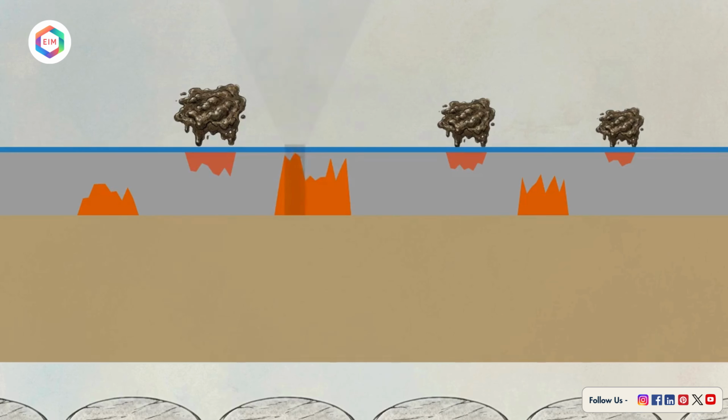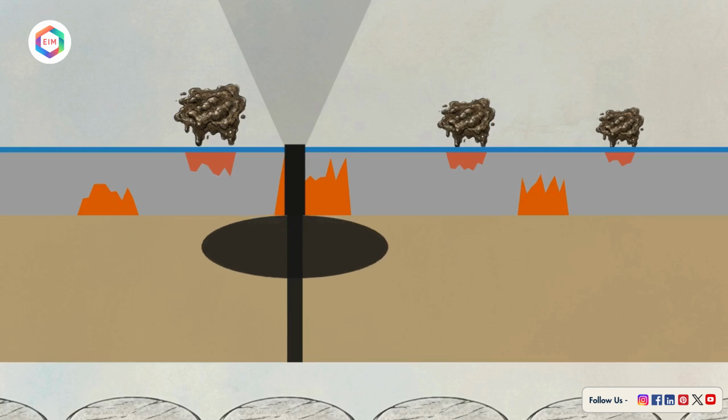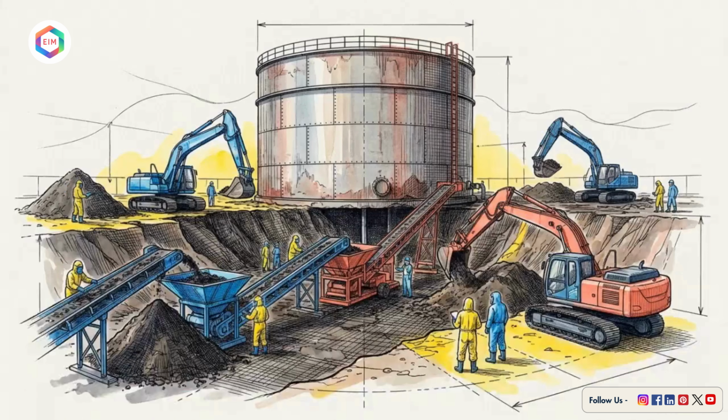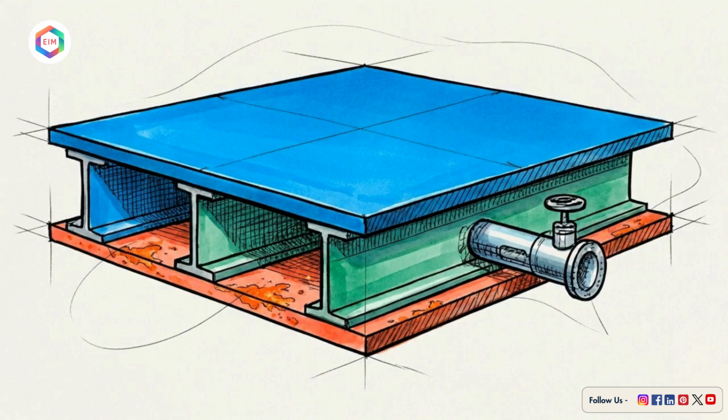If a soil side breach occurs, product releases into the subsoil long before a visible leak develops, creating an environmental liability that can exceed the cost of the tank. To mitigate this, many owners install a double bottom to provide an engineered interstitial volume for leak detection. This creates the credit trap.